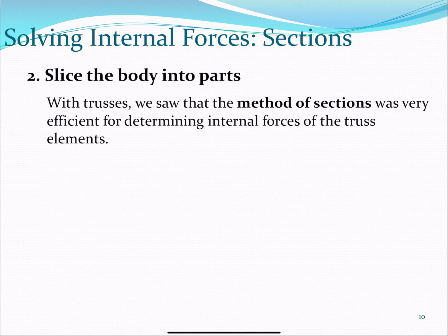So how can we calculate internal forces? Well, we're going to apply the method of sections, which we learned in the context of trusses. Remember, we divided the truss into two pieces, and when we divided the truss, we uncovered the forces in the two halves, and then we chose which half to analyze, and then we were able to calculate the internal force. So the first step, or the second step, is to slice the body into parts.